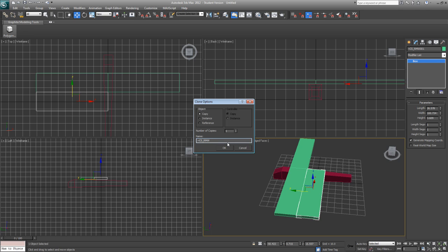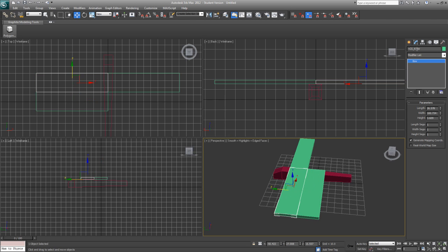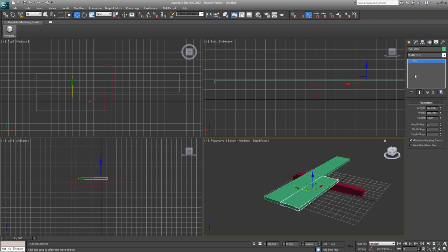This is the left. Okay, I'm caught up now. Alright, so I'm going to make this L, M, A for left main aileron. Click OK. We need to rename this to L, because I guess I don't know my left from my right. This one, R. Okay, now we can see that's entirely too long.